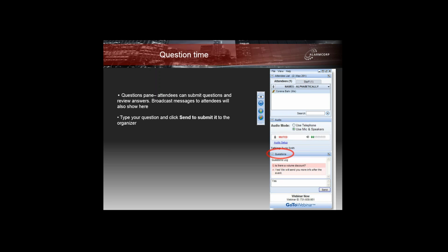Typically, the way to avoid any of that is to have isolation between those machines and the concrete structure, and that's pretty normal on just about any site. That's about the only application where you're likely to have issues with a seismic detector.